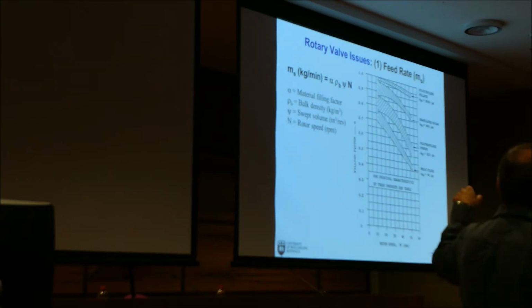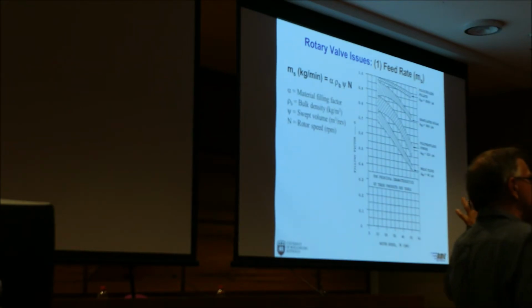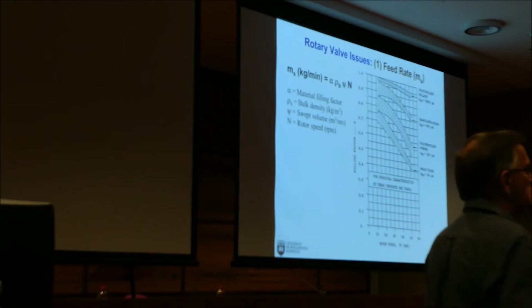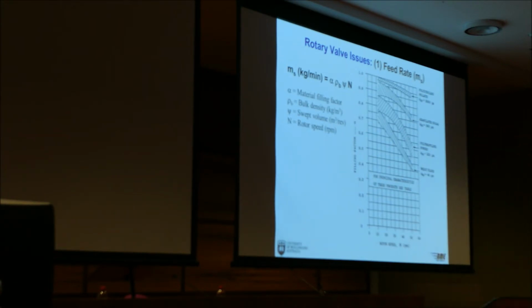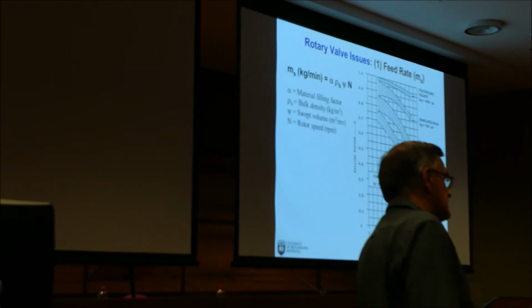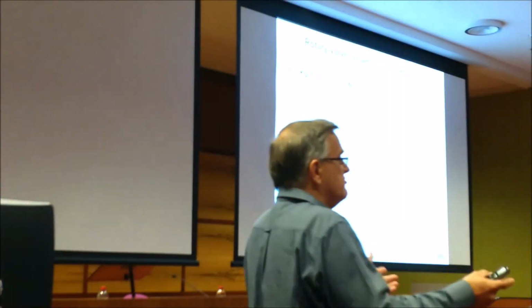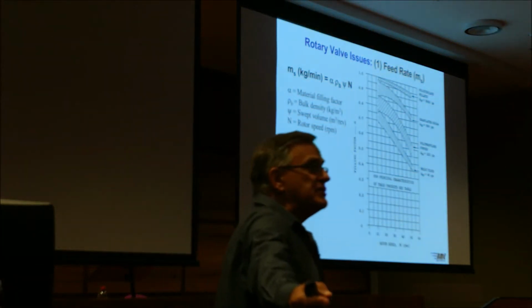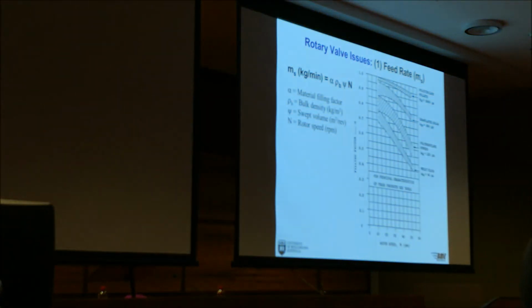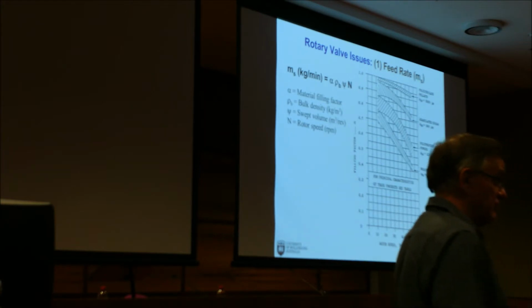If you look at the end of the notes, D50 is the median particle diameter. Averages can be weighted averages. If you go to mathematics and statistics, there are different ways of averaging things, depending on your distribution and all that sort of stuff. With D50, there's no ambiguity. D50 is just a D50. If you look up statistics, you'll see D50 there in mathematics, no problem, based on any distribution. So, if we run an exam in this room, you get a whole spread of marks, and you can work out what the D50 is of marks. What's the average mark, so to speak, the arithmetic average. Alright?